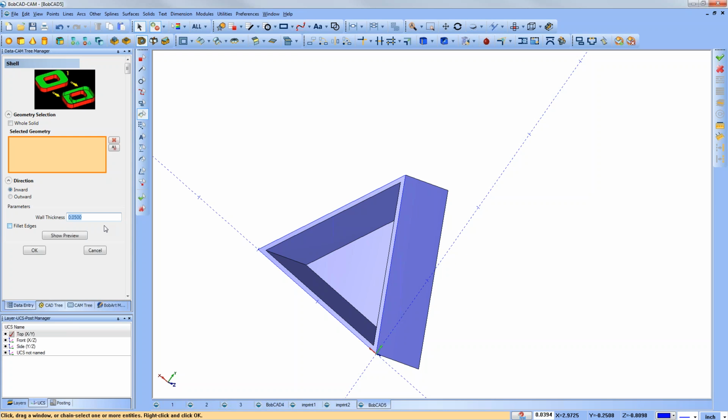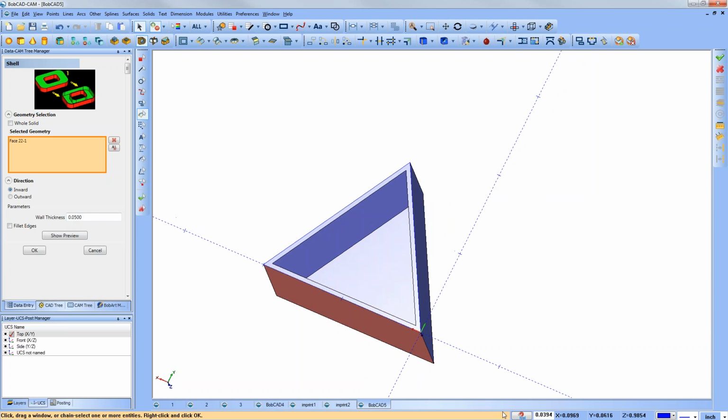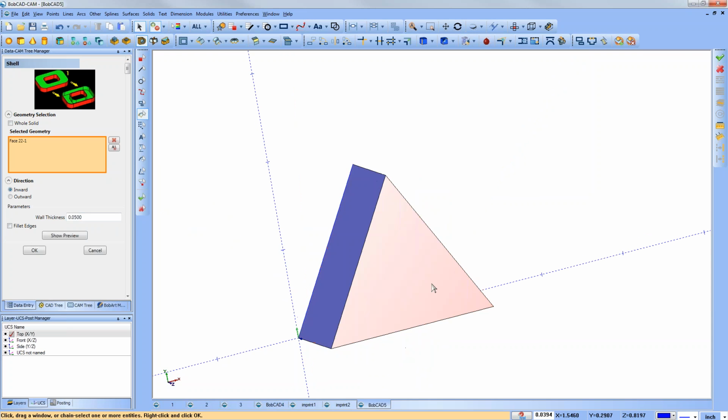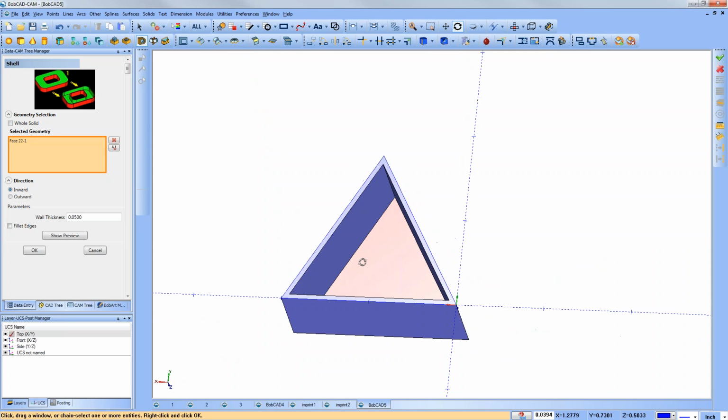If you wanted a different depth for this back surface, you'd have to do what I mentioned earlier. You wouldn't shell it, or you may shell two surfaces and leave it open, and then recreate something thicker. Or you do an extrude cut, offsetting, picking geometry, or creating this inner geometry and extruding cut down to whatever depth you want, leaving the sides 0.05 and maybe leaving half an inch.